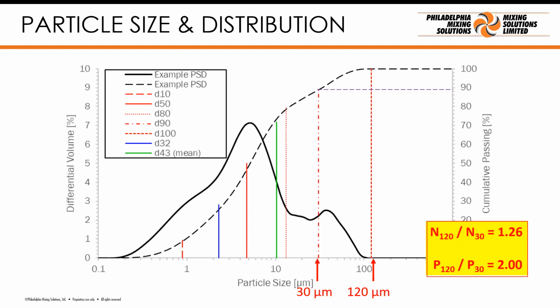So it becomes an economic question. If I'm going to leave these big particles behind, how often am I going to have to go in and clear out the tank? And what does that cost me? Firstly, to do the clean out, and secondly, to shut the plant down for long enough to do that clean out. Is it actually worth spending the money to be able to suspend the largest particles in the distribution? It's an economic question.